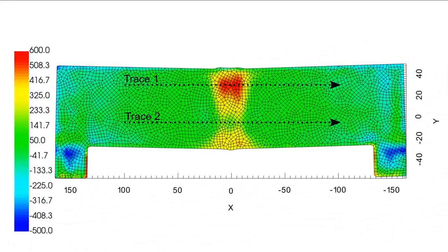After some fancy metrology and numerical analysis of the distortion stemming from the released residual stress, this was the resulting distribution. A big pocket of near-yield residual stress, some lesser tensile stresses, and again, this is all localized on the weld, which were balanced by compressive stresses on the outer edges and restraint. Running a pair of traces over this contour map, the one at the highest, trace 1, and trace 2, lowest in the weld, it looks like this.